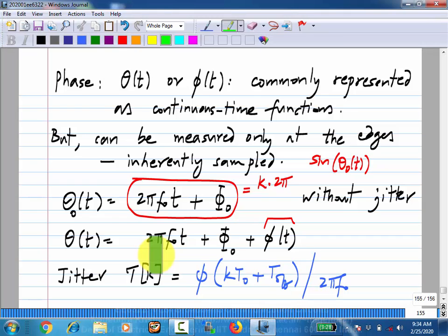Now we will try to model the CDR, basically the clock and data recovery circuit, get the incremental model of it, and from there we can calculate everything, like what the different values should be and how the phase noise or noise in different components affect the jitter, etc. Okay? Any questions here? I think everything that I said so far is probably familiar to you from communication systems courses. This is just a refresher, and then we will be using this heavily for modeling clock and data recovery circuits and phase lock loops. Okay.